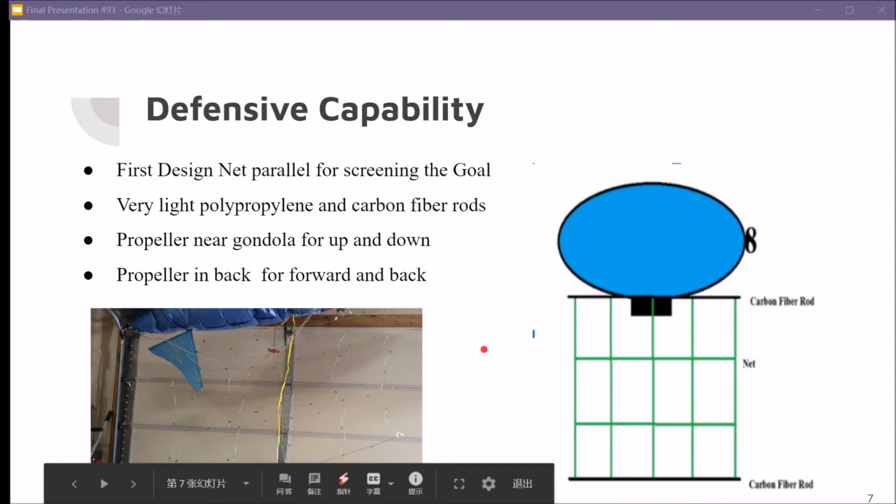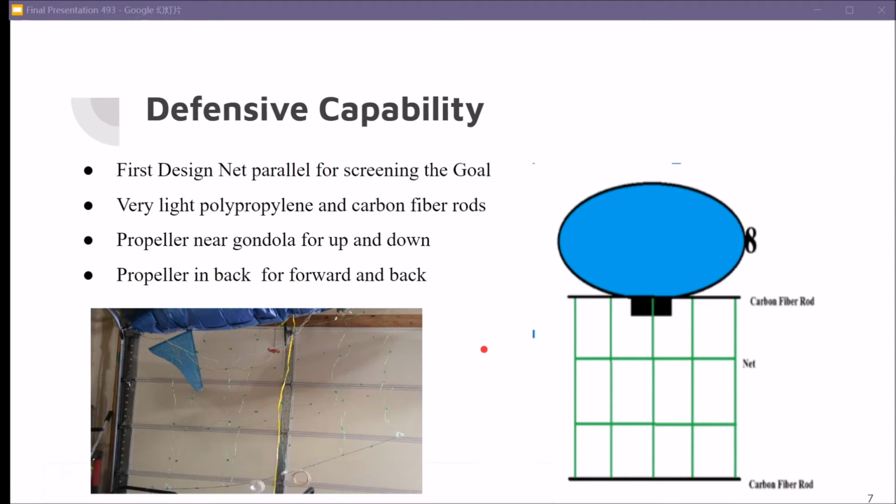The game size ball is 24 inches in diameter, so we calculated the max size of the net hole to have a minimum amount of net, yet still be possible to block the ball, with a hole of 11.4 inches per side of the square hole. But we used a smaller ball of 18 inches during the demonstration, so we went with a hole size of 8 inches at each side of the hole.